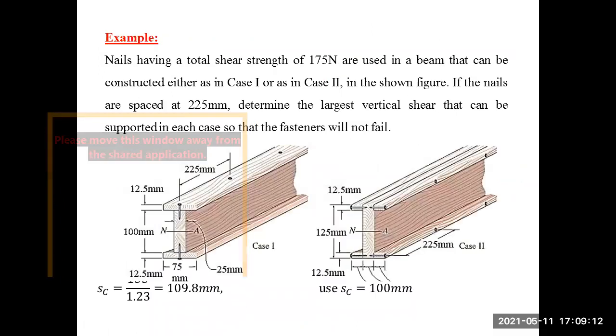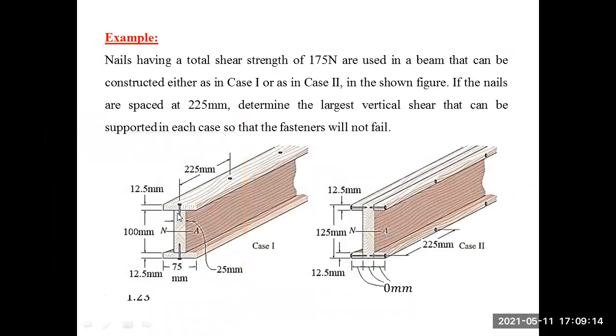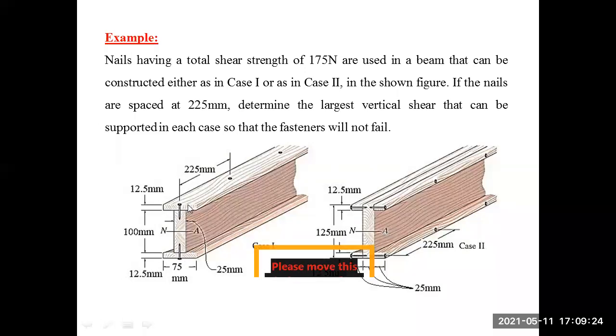You see that this I-beam is made up of how many components? One on top, one on bottom, and the web. So the flange at the top is not a single unit with the web. It's an independent component, so it has to be either glued or fastened using a rivet or a screw or whatever you want to use.